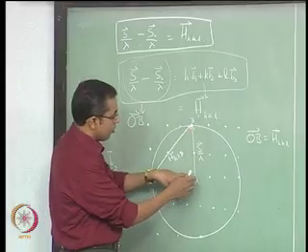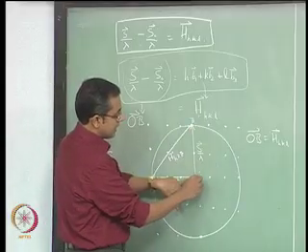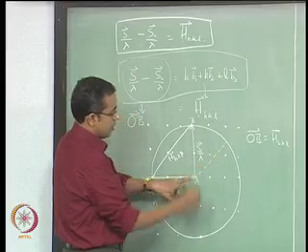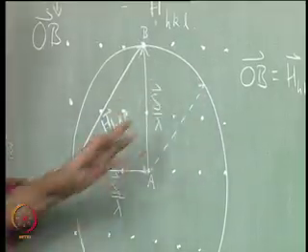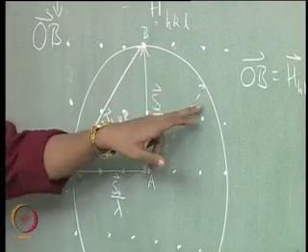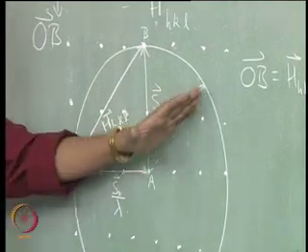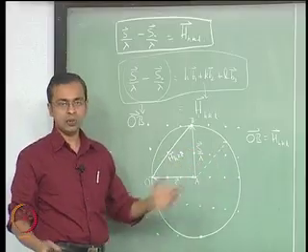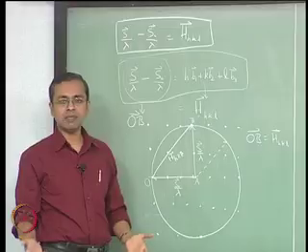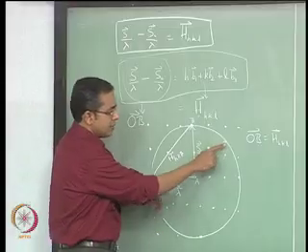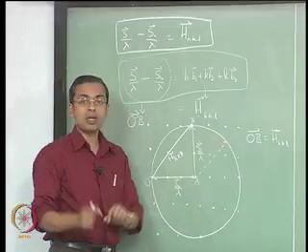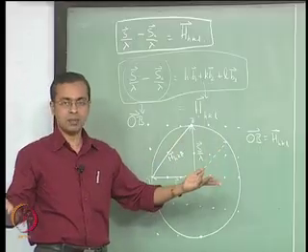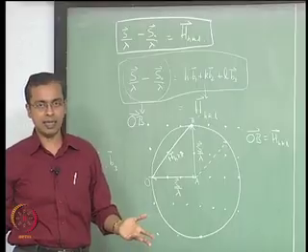So if you looked for diffraction in this direction, for example, I will just draw a dotted line here, okay. So this is another s by lambda direction, again the magnitude is still 1 by lambda, but it is in a different direction, so a different s, okay. So if you want to call this S1, that is the S2 direction. In this direction diffraction will not be visible for us, because the circle is not touching a valid reciprocal lattice point, it is simply touching a region in reciprocal space where there is no valid reciprocal lattice point.